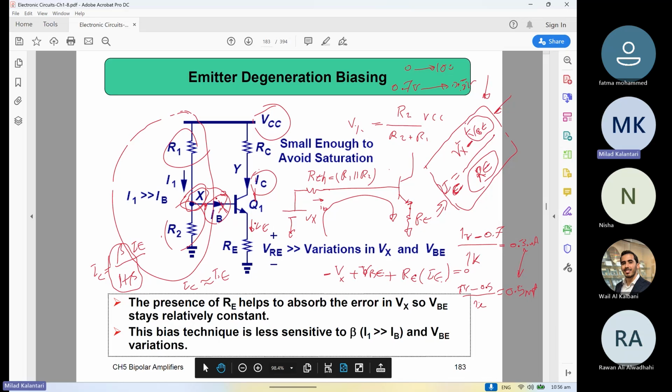So what you need to do is to read. No, this is the DC. That RPi and RO are for the AC model, right? So for the DC, we just care about the turn on voltage and the resistance value over here. So in this equation that we have, what parameter, if we change, can reduce the variation? The RA is not doing anything, basically, in terms of the variation. It changes the absolute value.